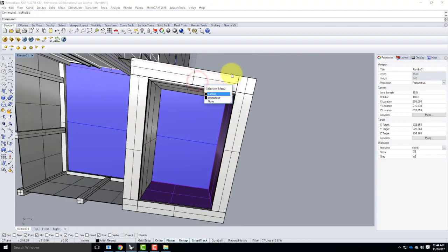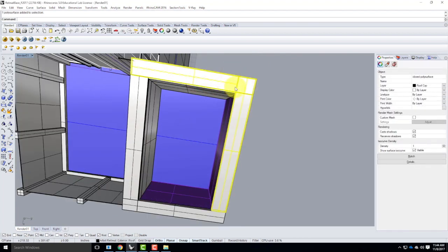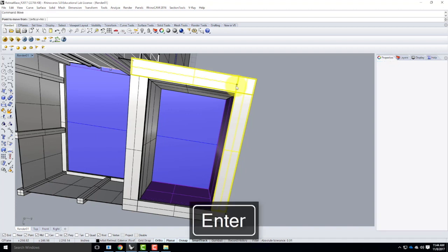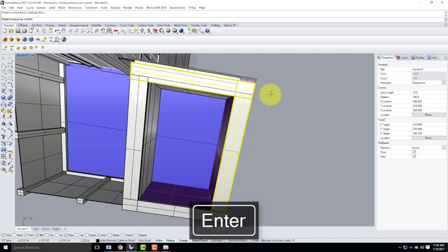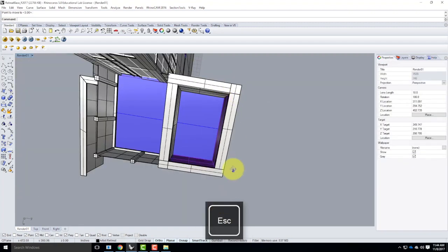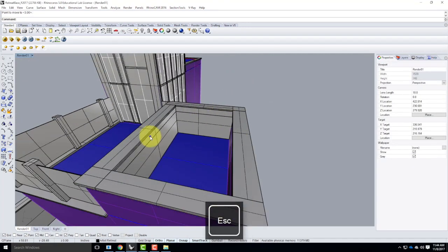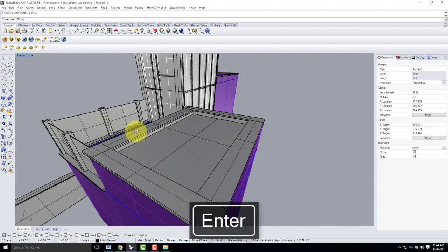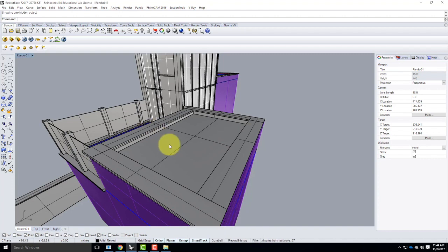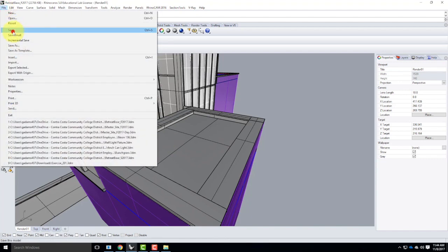Looks like that didn't quite line up correctly. Well, we'll leave it like that for right now. I have a little issue on the top there. So it's ready to render, but I need some light in this pool if I'm gonna render the pool. So I need to save this, go back to my master site file, and then put the rectangular light in. So I'll go ahead and go to File and then Save.